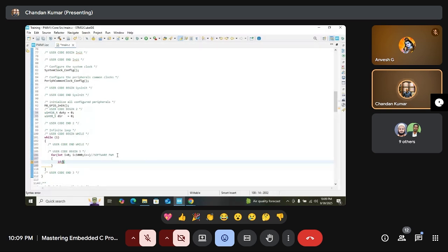For example, if it is reaching 100% brightness in 5 seconds, I am taking a loop and saying that for second 0 to second 2.5, it will turn on, and after reaching 2.5 seconds, whatever brightness it reaches, after that it will get diminished. So that's how PWM is acting there. Clear?